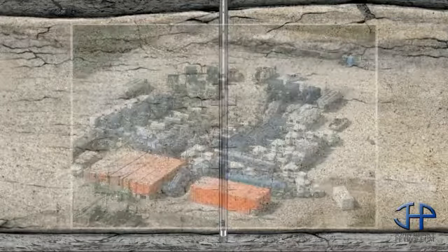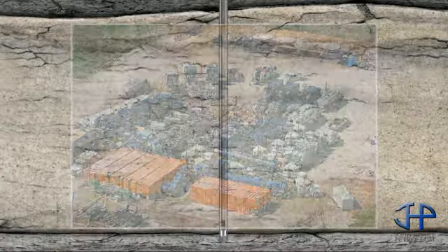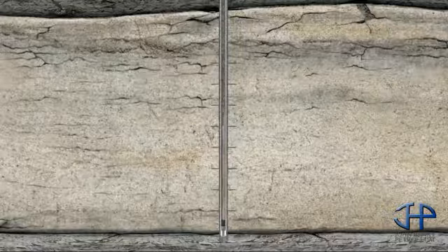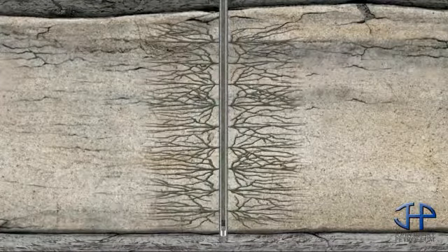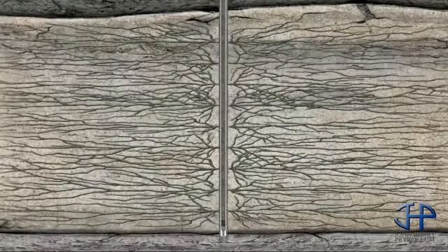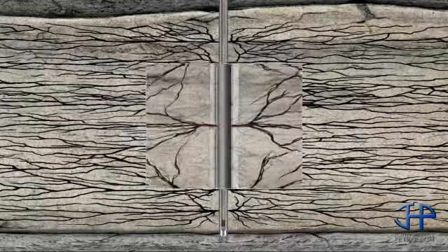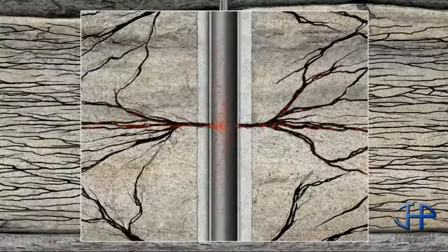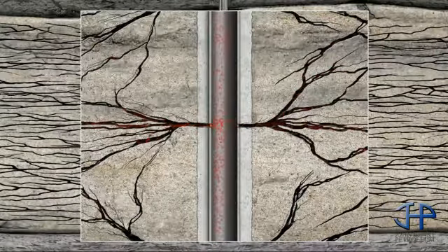The next step is to hydraulically fracture, or frac, the zone. Here, sand or other proppants are pumped into the wellbore under extremely high pressure. When the mixture reaches the target zone, the pressure forces it out through the perf holes and out into the sandstone formation, causing it to fracture. This creates a fairway connecting the reservoir to the well, inducing the released gas to flow to the wellbore.